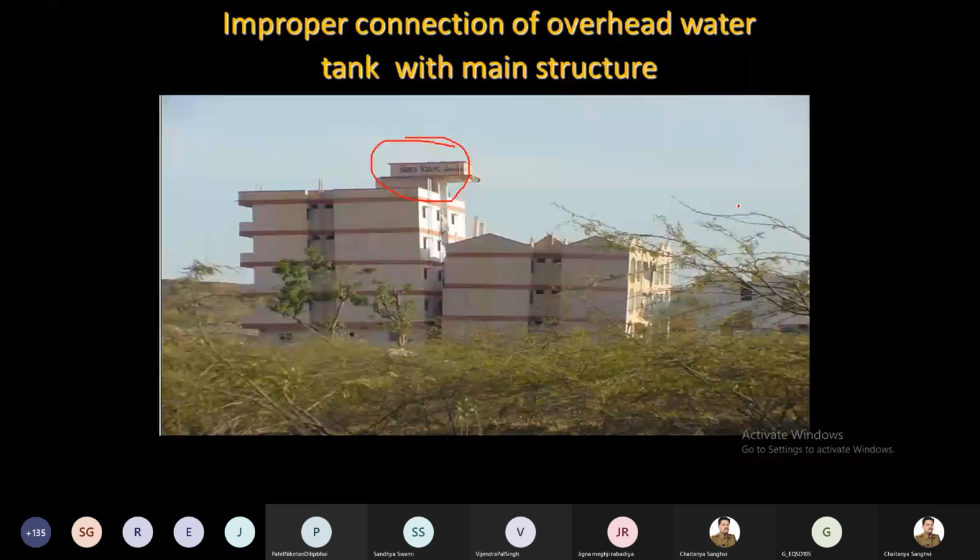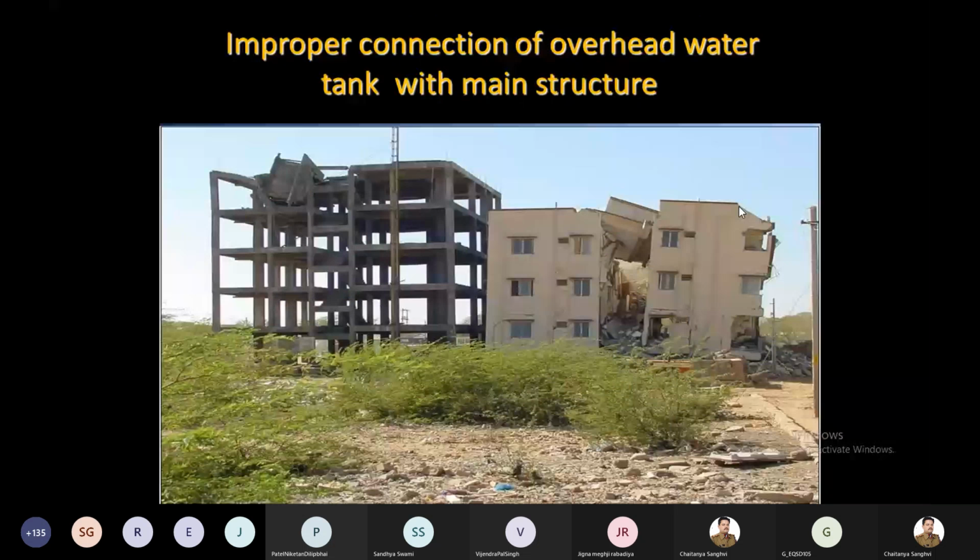You see, when we are placing our water tank on 4 columns, basically this water tank is okay as far as the vertical load is concerned, but when an earthquake comes, it is going to shake in the horizontal direction, so it behaves like a cantilever. So this water tank is actually a cantilever supported on 4 columns, right? And this collapse you can see here, this collapse had been observed.